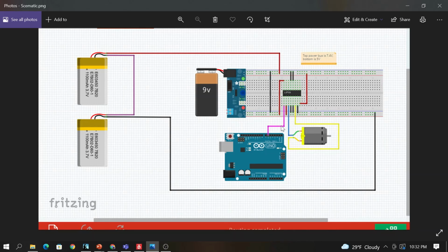How this works is like this. If this pin is set high and this blue one is set high, the motor's going to run. Okay? If all three are set high, the motor's going to go into a stop mode. And that's how we do it. Basically, we're switching registers on and off to tell it what to do.